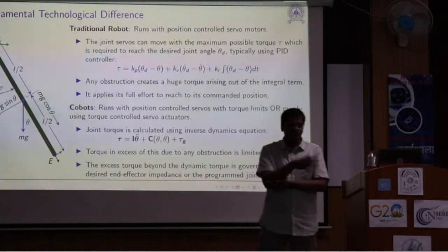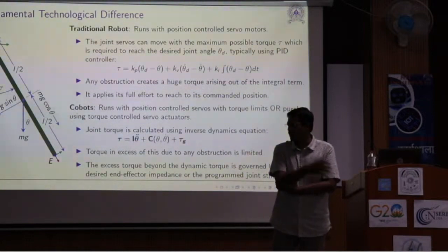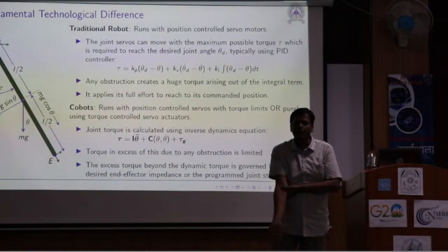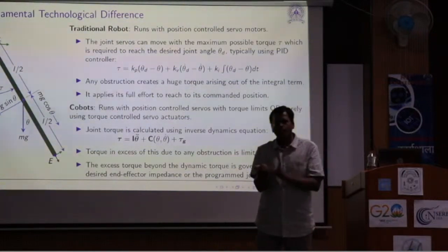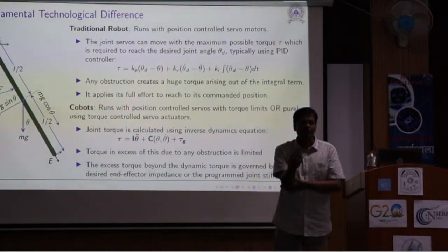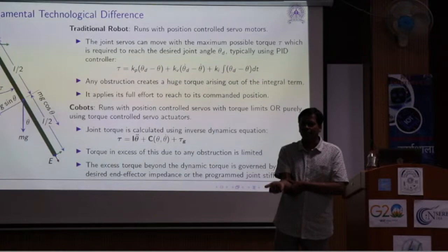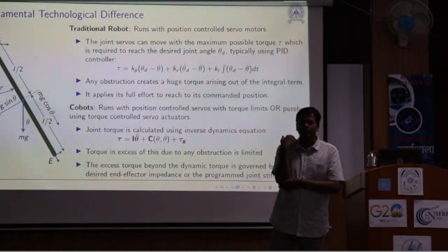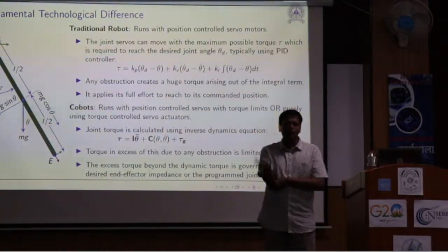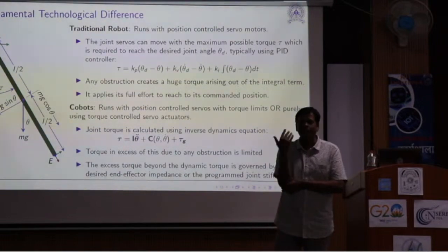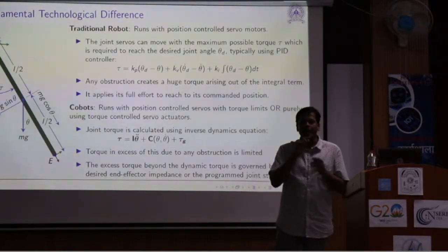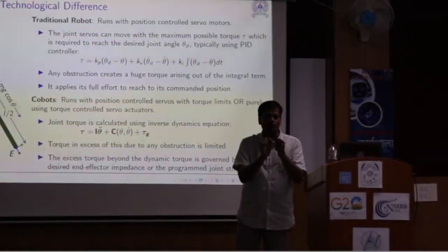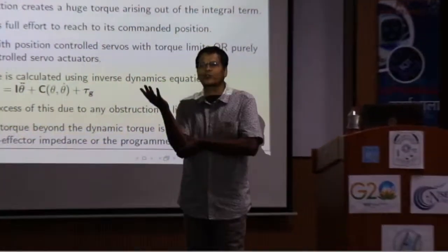Again, another way to drive it is you have a link which is fully defined. I know its center of mass location. I know its masses, right? Moment of inertia tensor, not just scalar inertia, right? So you know the inertia, right? And now you are doing what? You are just commanding to go to a place using a torque command. And I am giving just enough amount of torque so as to reach a particular angle.